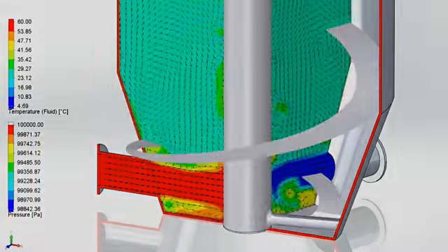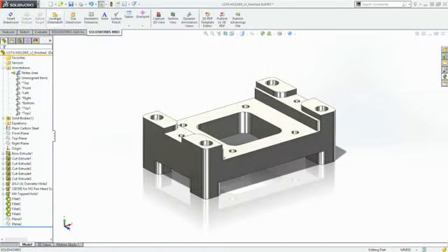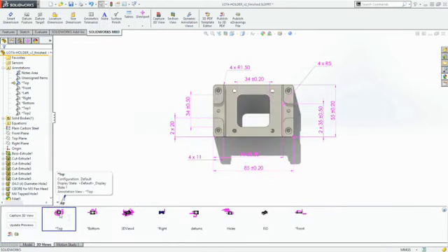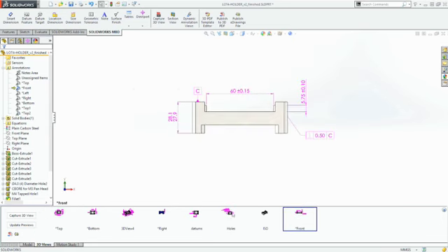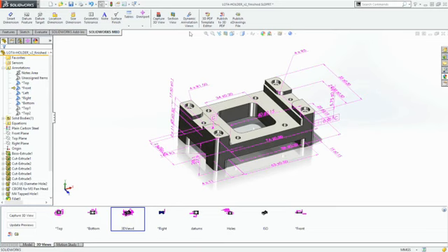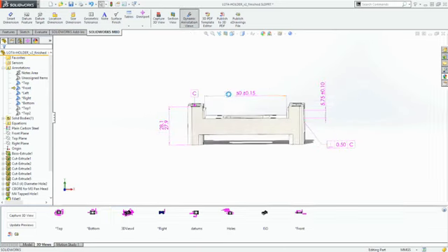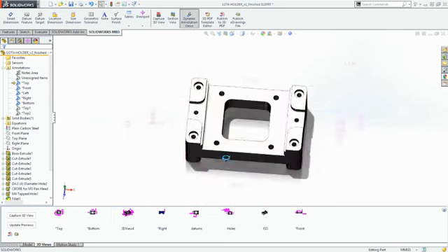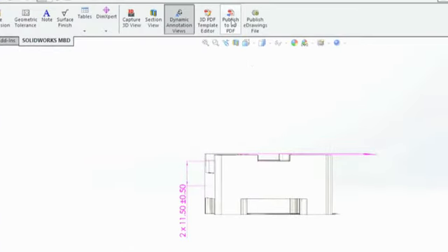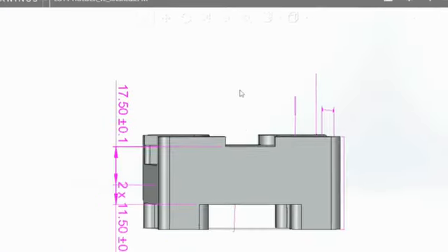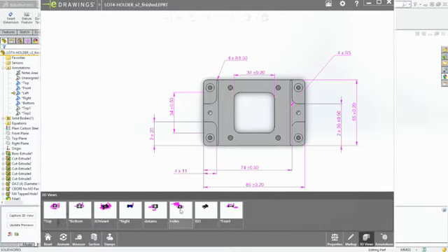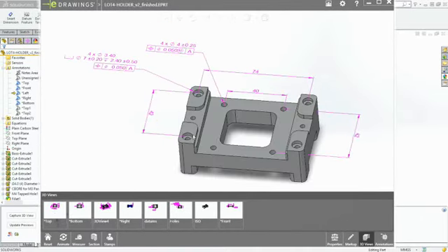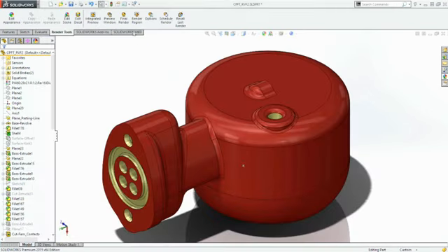Solidworks MBD defines 3D PMI, such as dimensions, datums, geometric tolerances, and other annotations within the Solidworks 3D environment. 3D views organize PMI data into clean and structured presentations with different views and display settings, such as configurations and display states. These 3D views can be shared using industry-standard formats, such as eDrawings and 3D PDF, helping others in the supply chain understand the design without a 2D drawing.